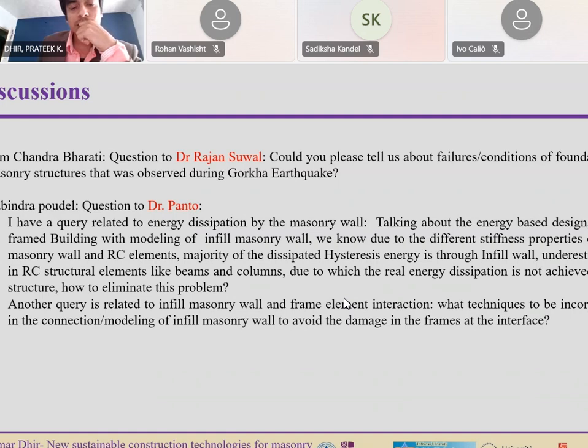In the masonry buildings, whatever we observed, there was not a lot of problem in the foundations; the main problems were out-of-plane, in-plane and shear. We found most of the masonry buildings had out-of-plane failure. This is because the connection between the main wall and transverse walls is not proper; they are not properly connected.